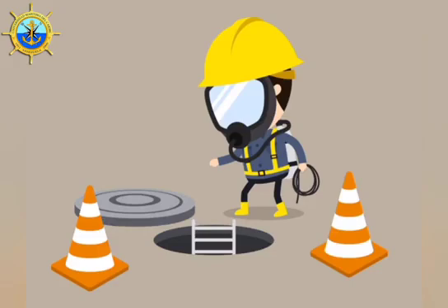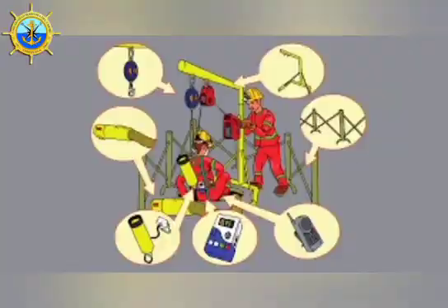Before entering a confined space, a series of prevention and safety measures must be carried out: ventilation, localized extraction, and respiratory protection. At the time of entering, we must follow the following steps. Atmospheric checks before entering. Effective ventilation will be continually maintained. Employees entering a permit-required confined space must wear the appropriate personal protective equipment for the condition of the space and the work to be performed.